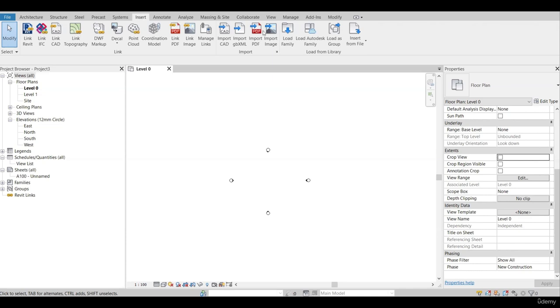But whenever you import something, even if the source file gets its data changed, there won't be any change visible in the Revit imported file, because there is no link between the previously imported file and the recently saved file. So whenever you have any data change or possibility of data change with respect to any of the file formats that you are importing, it's better to go with the link option rather than the import option, because even if there is a change in the main source file, those same changes would be incorporated into the linked files, and the same results would be shown in Revit. So you don't need to check again and reinsert those files back into Revit again.